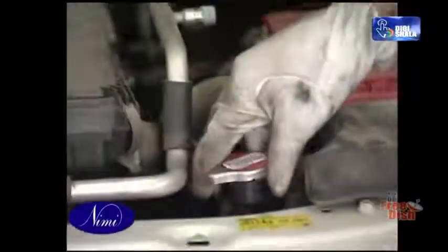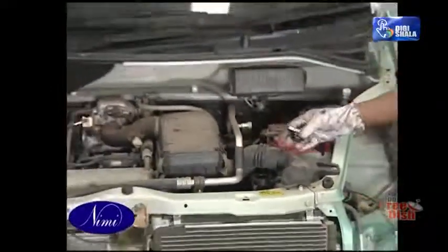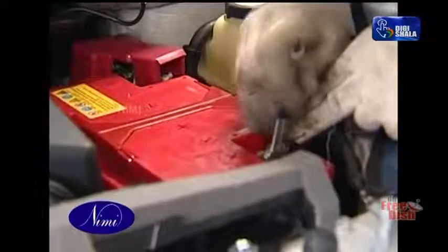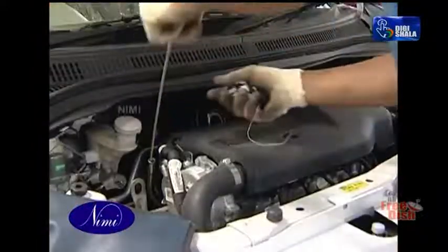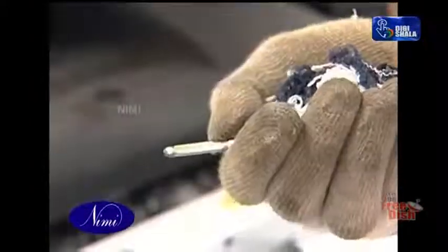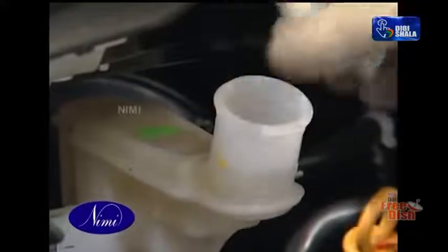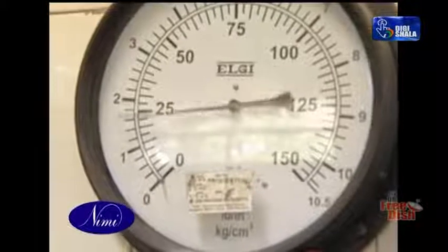Check the water level in the radiator, the battery terminal for any corrosion or looseness, the engine oil, the brake fluid level in the master cylinder, the air pressure of the wheels as per specifications, the fan belt tension,